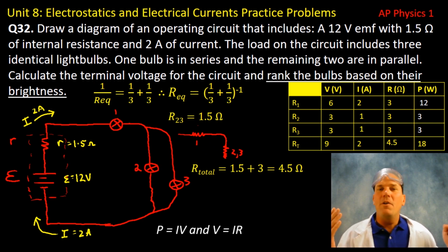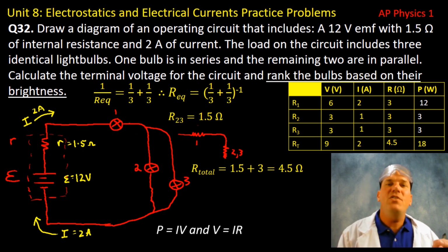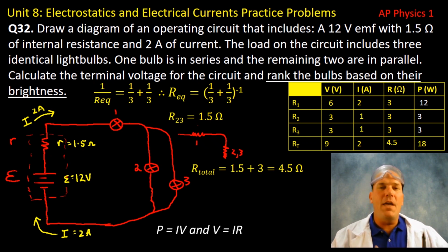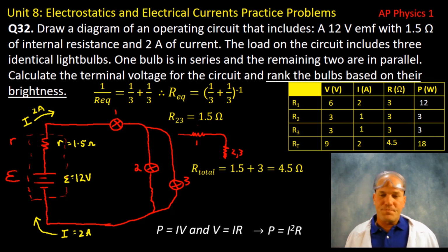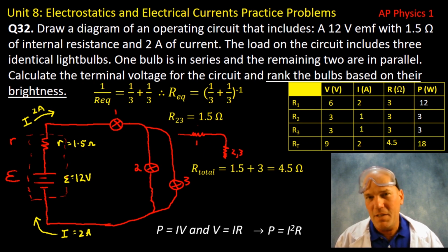All right, so we know power is equal to current multiplied by voltage, and we know Ohm's law, and we also know that you can rearrange Ohm's law and insert it to solve for power and all kinds of different things, really, about electrical circuits. So let's go ahead and take IR and substitute it in for the voltage and get this simple expression that we've talked about in class, where power is equal to the current squared multiplied by the resistance.